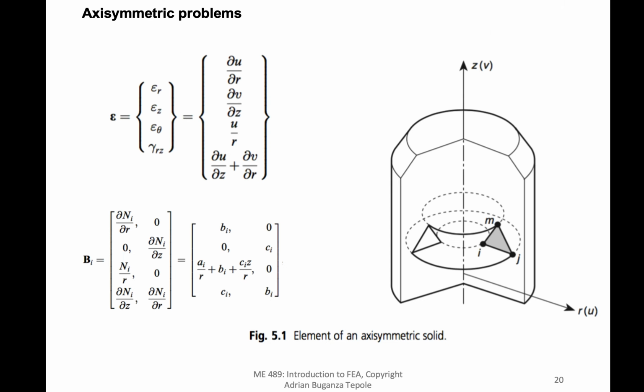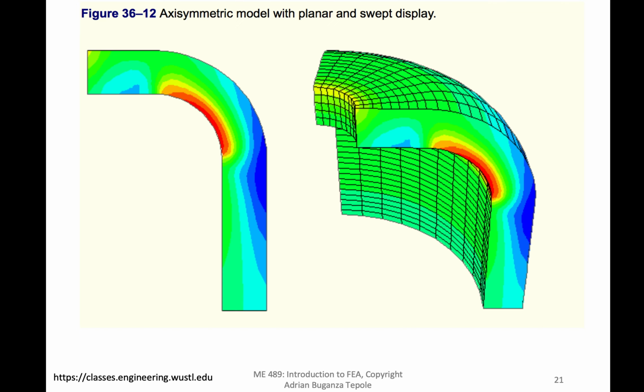Another thing that I said last lecture as well is that whenever possible, you want to simplify your problem. Instead of doing the 3D elasticity problem, you want to do plane stress, plane strain that we have talked about, or an axisymmetric problem. So Abaqus has some capabilities of doing this. So you can use axisymmetric elements. We didn't really talk much about them, but they are in Abaqus.